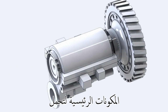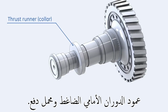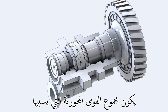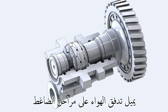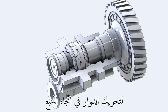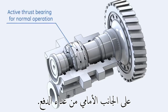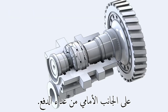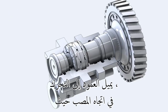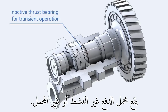The thrust-bearing major components are the thrust runner, which is integrated in the compressor rotor forward stub shaft, and 2 thrust bearings. During the normal operation of the gas turbine, the sum of axial forces induced by the airflow on the compressor stages and the hot gases flow through the turbine stages tend to move the rotor in the upstream direction, so that the active thrust bearing is located on the forward side of the thrust runner. While in the transient operation during startup and shutdown, the shaft tends to move in the downstream direction, where the inactive or unloaded thrust bearing is located.